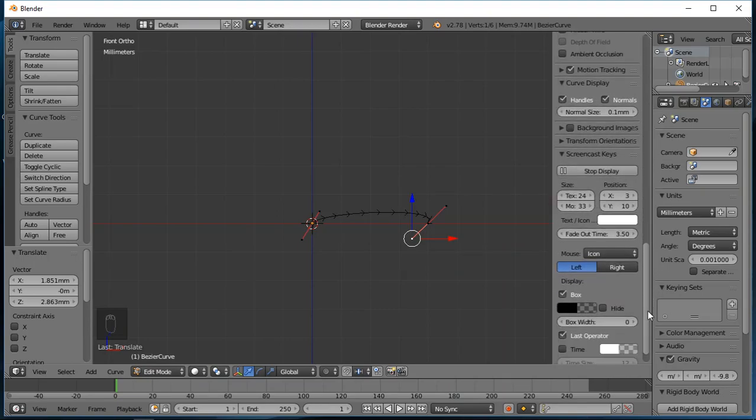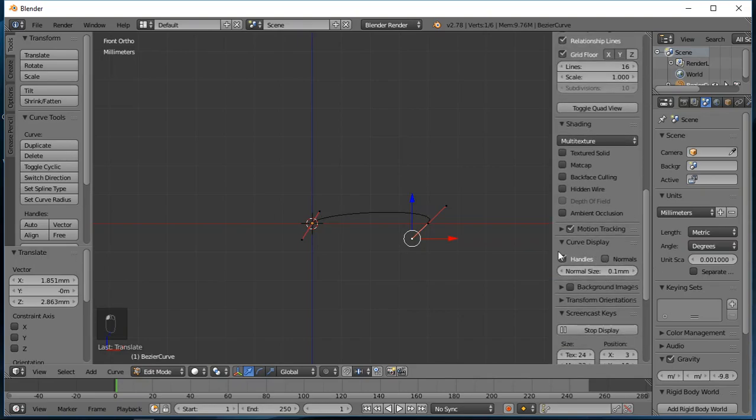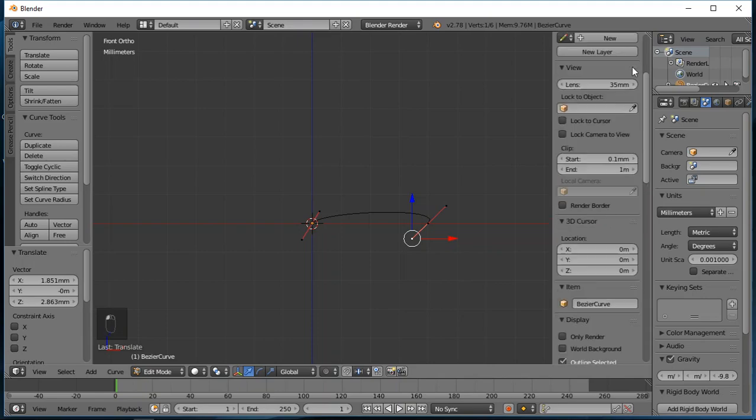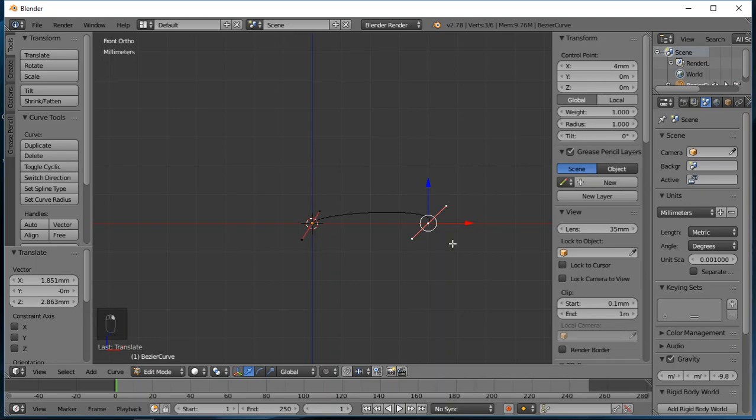I don't really want to see those arrows on the line, so those normals. So I uncheck those in that toolbar, transform toolbar. So now I can add, so I have that second vertex on the right at 4, 0, and that will take up the radius of the bore. The bore of the fidget spinner bearing is 8 millimeters, so going from the center of the fidget spinner itself to the edge of the bore is 4 millimeters, so I have the x coordinate at 4 millimeters.